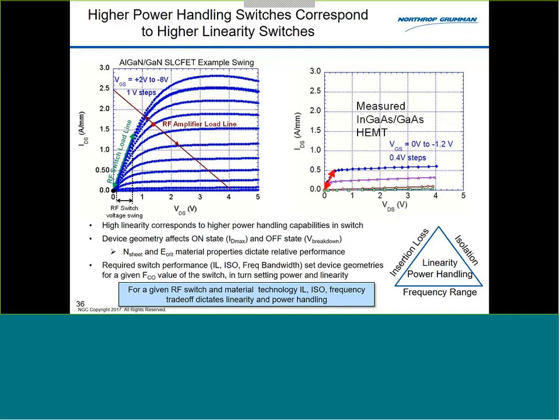So in the conventional GaN device, I have a single heterostructure, and I'm using a MESFET essentially, so I have a Schottky gate on top of that. And you're absolutely right. If I forward bias that, I'm just going to turn that Schottky diode right on. I'm going to see a lot of gate current. Now, some people make MOS GaN devices. Of course, they're not really all that great because you just don't get the same kind of charge density.